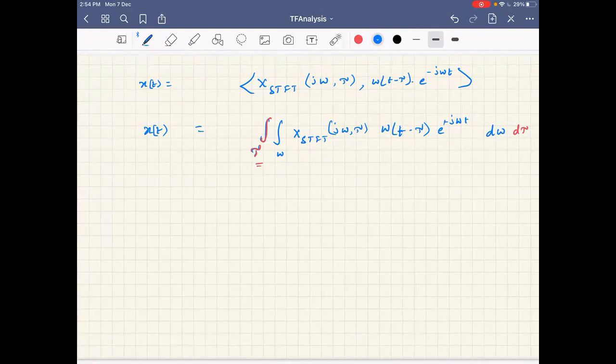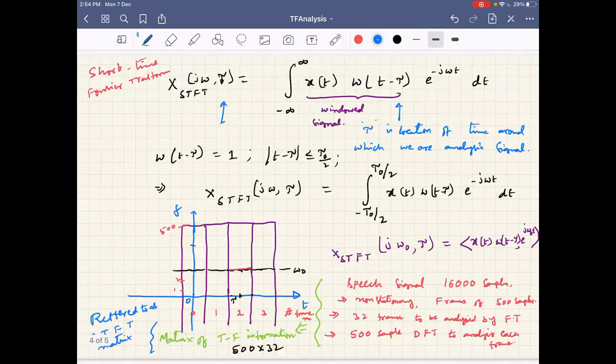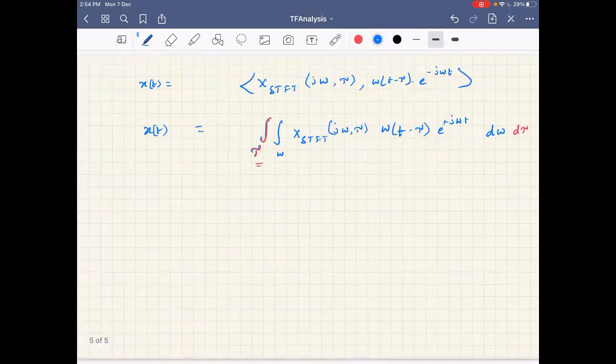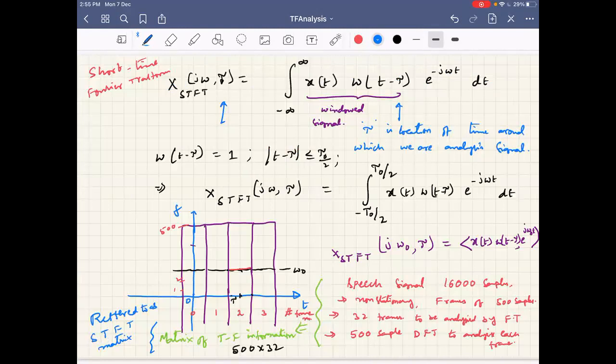So now the question is, is this short time Fourier transform itself good enough for the analysis of time frequency information, or are there better ways of extracting time frequency information in non-stationary signals, or signals having different frequency content at different durations or at the same duration? The answer is that the short time Fourier transform is a basic and simple approach for finding the frequency content at a given duration, but there are much more elegant methods for time frequency analysis, or localizing the information of time and frequency in a given signal.